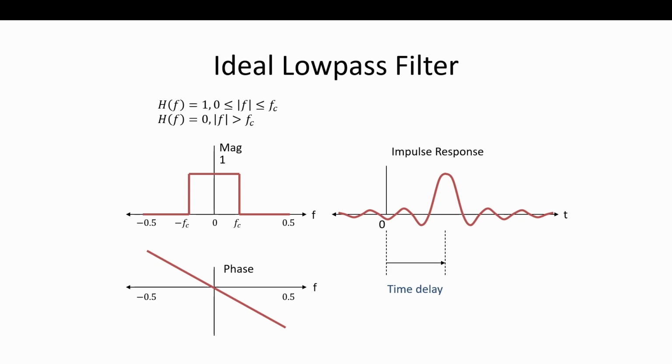If you try to do that with something that's nonlinear phase, then you have different frequencies at different time delays. So when you add up all those components, it's going to be a big mess. That's why we need equalizers. This is what a regular wireless channel would look like, in terms of the different delays. So that's why we like these filters, and it's convenient because they're the easiest ones to make. So is that clear? Because that's an important takeaway.